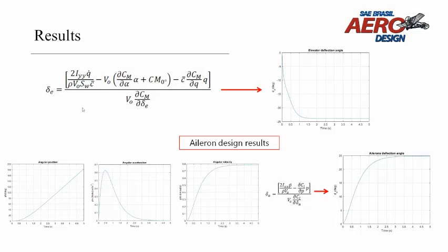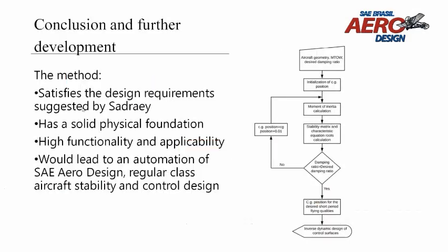is achieved. To conclude, I would like to mention that this technique is able to be assembled in a large iterative process to design the whole stability of an aircraft, at least for the short period dynamics, which are the most important for SAE Aerodesign, as long as the long period motion takes a large time to develop, and the mission profile of this kind of aircraft is not longer than 3 to 5 minutes.